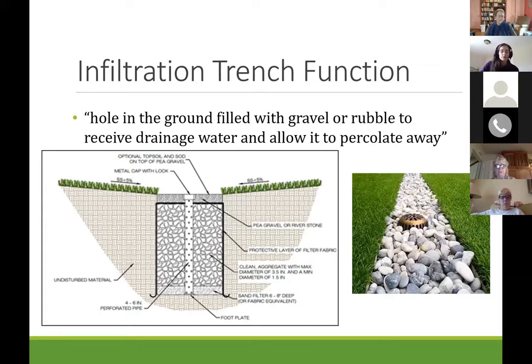So there are many different systems, but these are basically just big holes in the ground that we dig to a certain depth where we can get better draining soils. For the most part, our soil scientists in our area know that people frequently go out in your yard to try and plant a plant, and we've got that Virginia clay everybody talks about. But with these systems, we think about trying to get a little deeper than just the shallow surface, about 2 to 3 feet down. If you dig down a little further, in some areas of the county, you're going to get more freely drained soils.